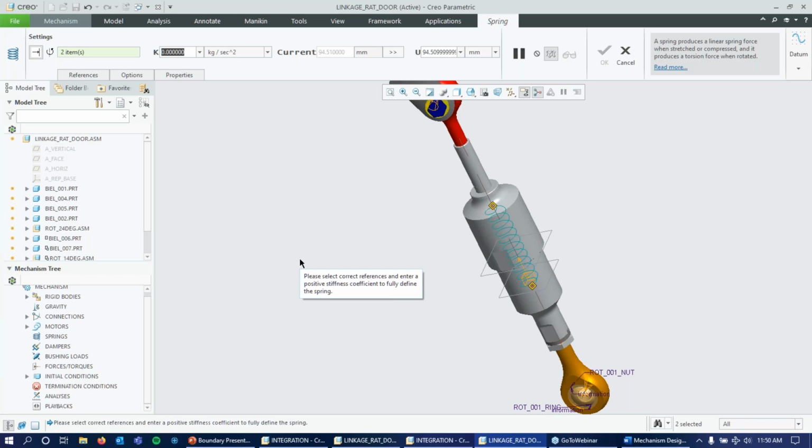If it was 0, that means your spring would not put any pull on anything, even when stretched. So it's kind of just like a coefficient that you multiply your distance by to determine the force. And every material will have its own K value. So we're going to use 100 for the spring. And then U is the base length of the spring, so that's the length when just not stretched by default. So I'm going to set that to 60.